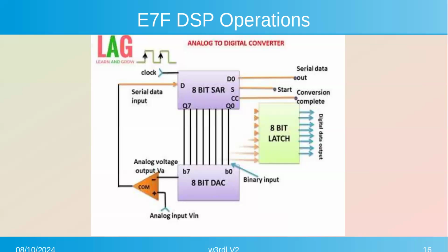That's why they call it successive approximation. So you keep going through it in binary. Essentially you're just trying every value to see whether it's greater or lower, and come up with the actual digital representation of it. They work very well. They're very accurate. They're slow. Depending on how many bits, you have to go through those steps for every sample.